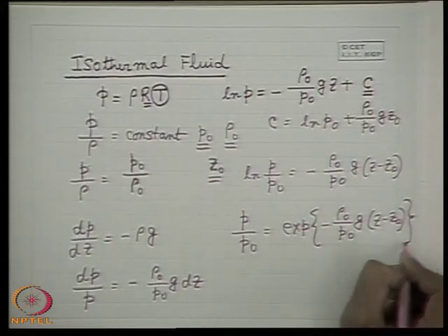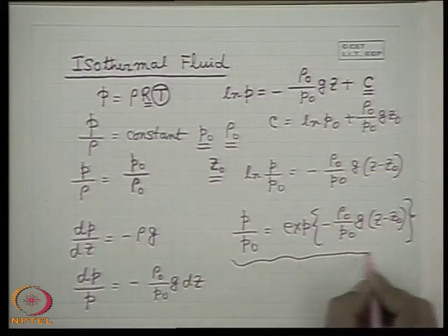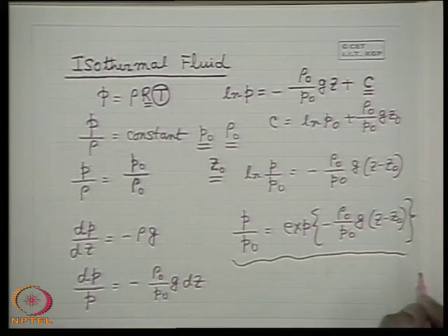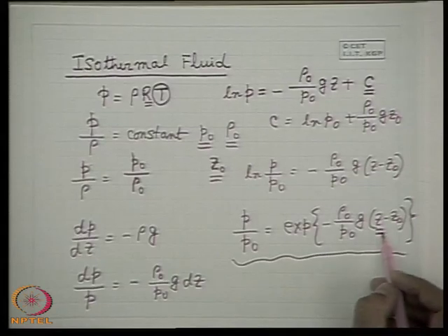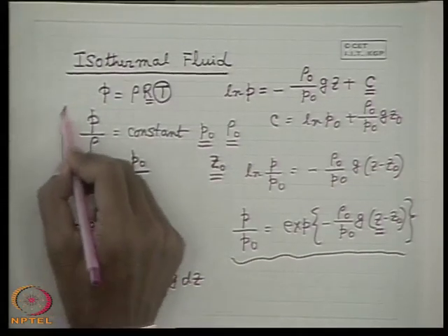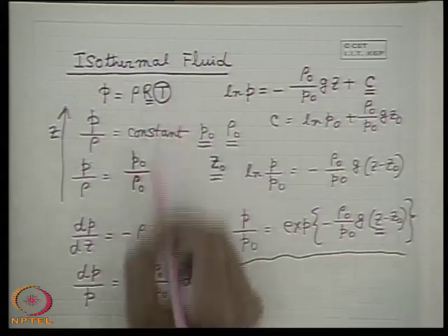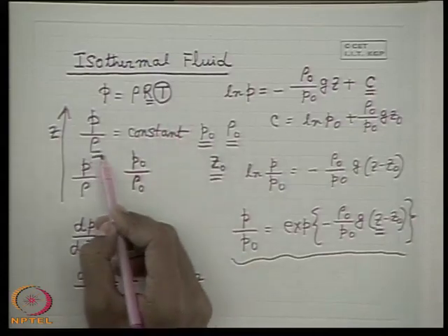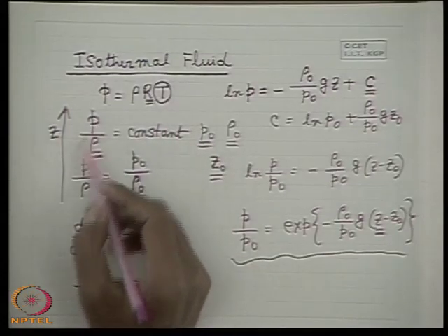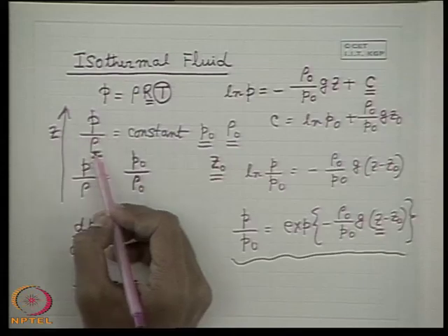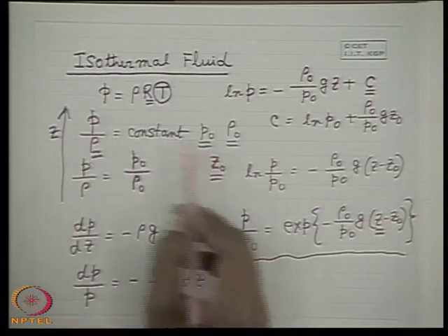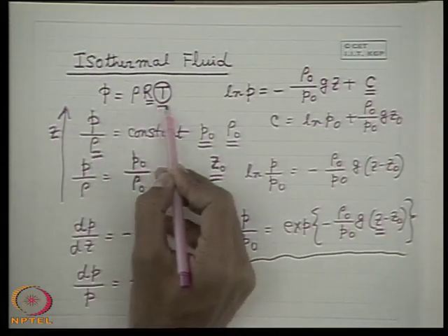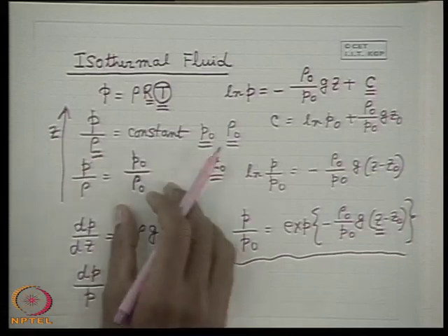So there is nothing of fluid mechanics, it is only a mathematical exercise through which we can find out the variation of pressure with the vertical height z, in case of a compressible fluid where density changes along with the change in pressure, in a fashion that the temperature remains constant,